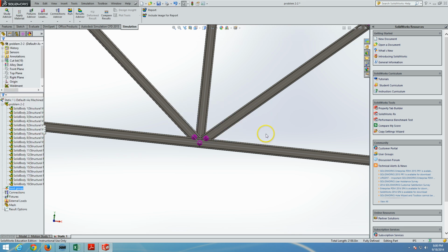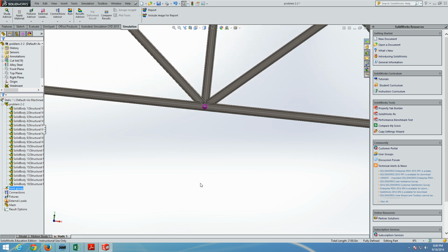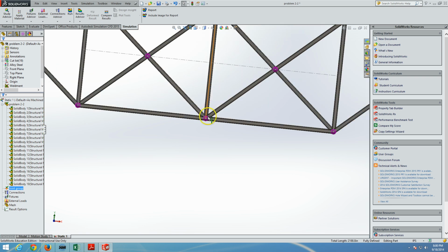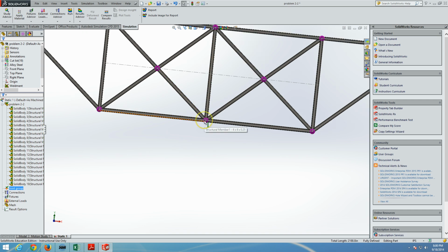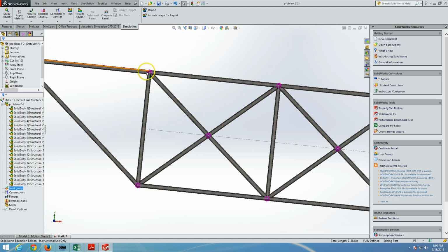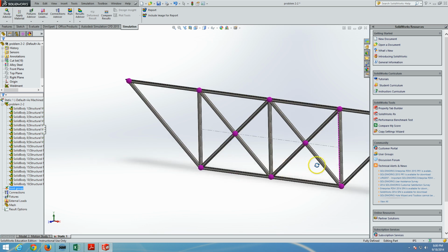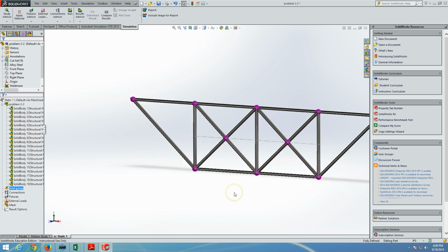Joints are. Aha, look what happened. As we increase the spacing for a single joint, those mitre cut elements were joined together. So now if we check this structure, you can see that every single joint is correct.